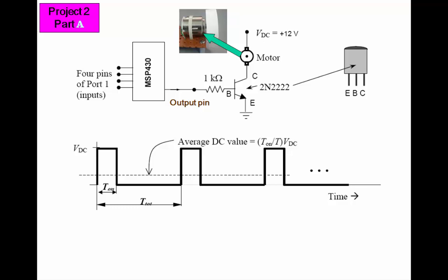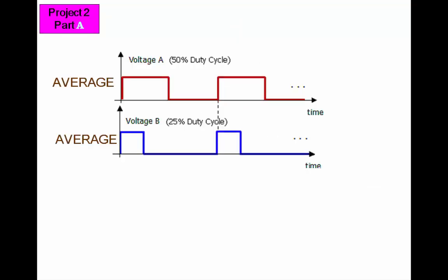The idea of this lab is that the motor speed will be determined by the average of the voltage that's applied to its terminals. Now, because the motor responds relatively slowly, we can apply a set of pulses that have an average DC value. If the pulses are fast enough, the motor will interpret that signal by way of the average DC value that is applied.